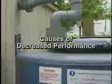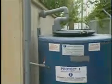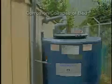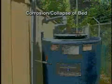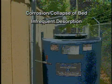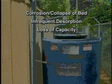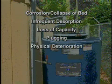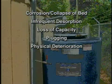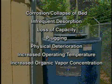There are several factors that contribute to the loss of performance in an activated carbon adsorption system. These problems include corrosion of the carbon bed support and subsequent collapse of the bed, infrequent desorption, loss of capacity due to the accumulation of condensed organic material, plugging of the activated carbon bed with particles, physical deterioration of the carbon granules, increased operating temperature, and increased organic vapor concentration.